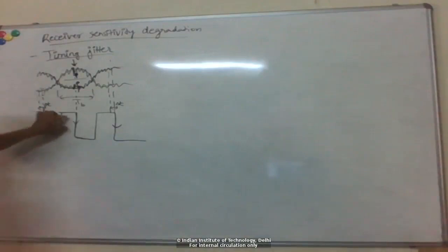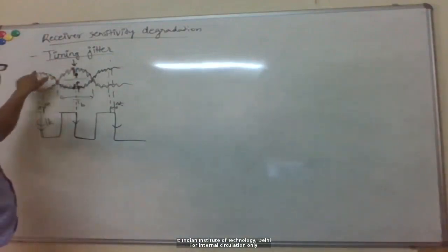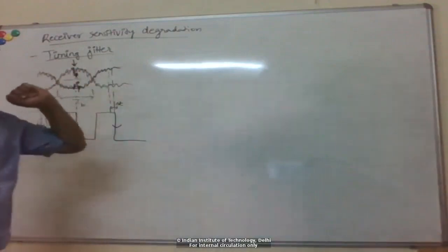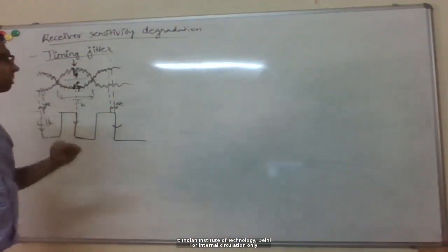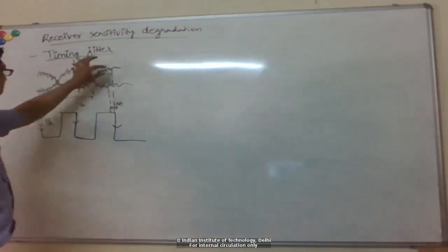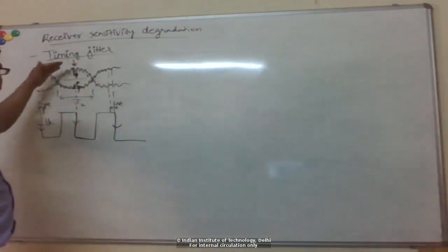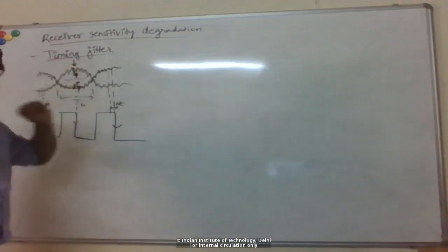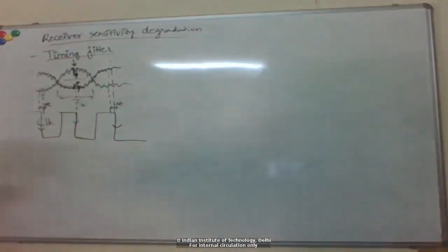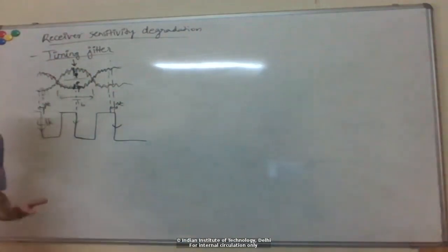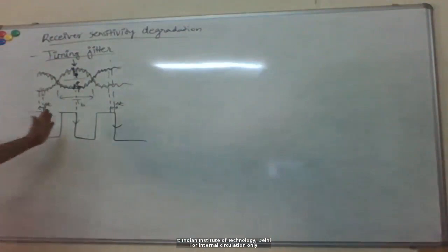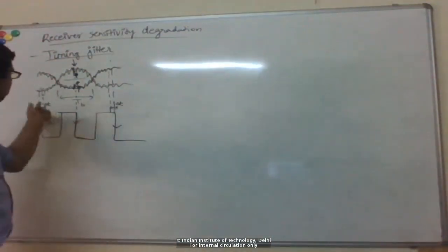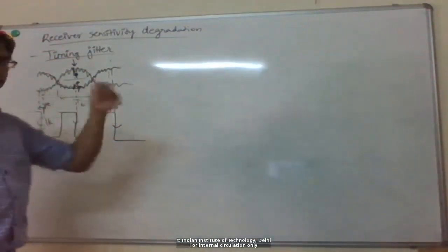The frequency that I get for the clock is derived from my bit stream itself. So if the bit stream was perfect, I would recover the period of the bit stream exactly. But since the bit stream is noisy, you have dispersion, you have noise added onto the signal, so the recovered clock is not exactly periodic. That's the point. The period is shifting up and down randomly by small amounts from bit to bit.